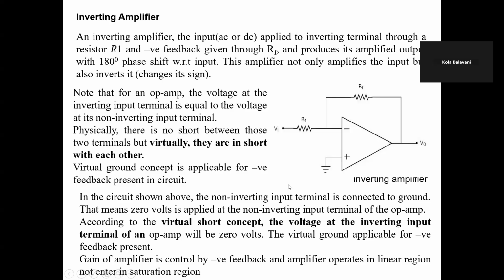The operational amplifier follows the virtual earth or virtual ground concept for doing any operation. The virtual earth and virtual ground concept means that physically there is no connection, no short between the two terminals, but virtually they are shorted with each other. Here the inverting terminal and non-inverting terminal follow the virtual earth concept.